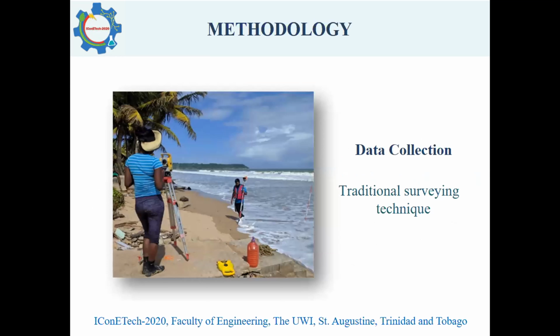The primary data collection utilized a traditional surveying technique to observe wave runoff positions along an identified cross-shore transect marked by 6 50-centimeter long PVC pipes driven into the beach face. Once the runoff positions were visually observed along this cross-shore transect, their vertical elevations were measured using the total station and prism method, referenced to the WGS 1984 datum, and later reduced to the still water line using the tidal elevations of the data collection during that period.